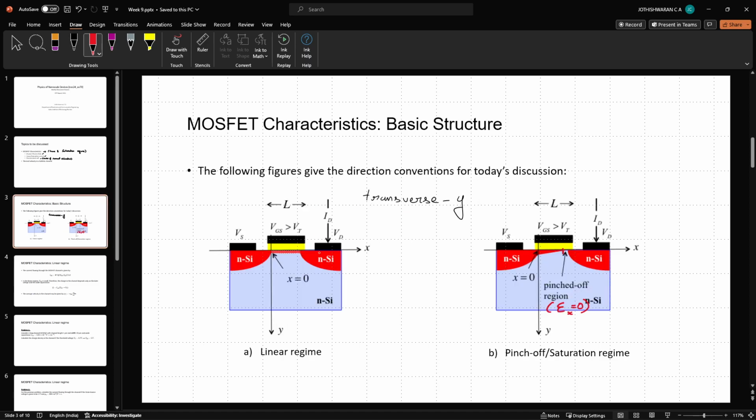The reason for that should be apparent from this figure itself. The actual region where current carriers are present is a very thin slice in the substrate. That is the small inversion layer. It's not even an inversion region, that's why we call it an inversion layer. It is so thin that if the electric field, or rather the applied voltage, increases beyond a certain point, we kind of lose that layer. So for all intents and purposes, even in a 3D MOSFET, like a bulk MOSFET, the area which contains the current carrying charges, the mobile charges, is effectively two-dimensional. So this is actually a quasi 2D space.